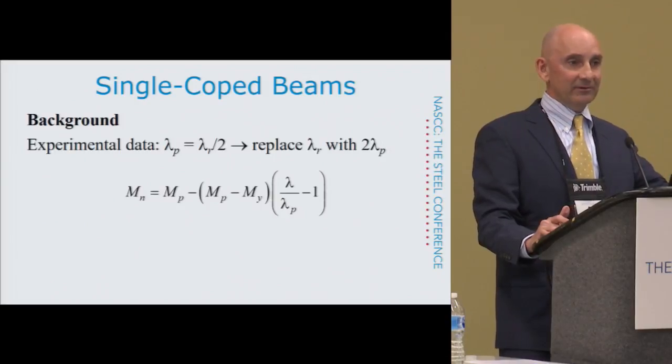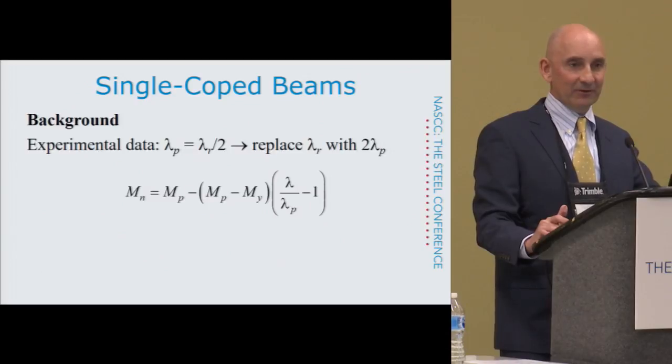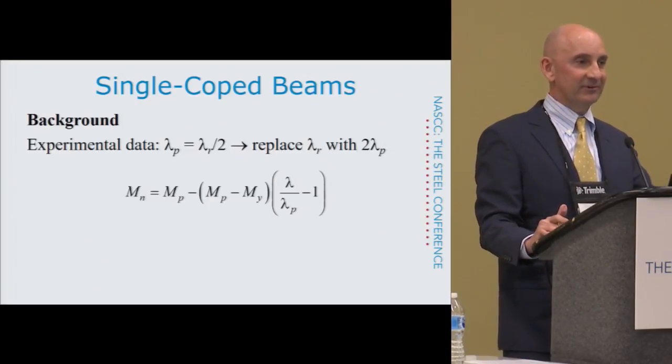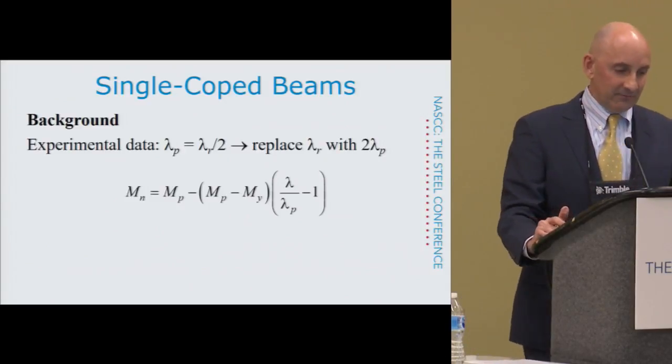Lambda_R, you can define using theoretical results, plate buckling equations with a fudge factor in there to account for residual stresses and out-of-straightness and things like that.